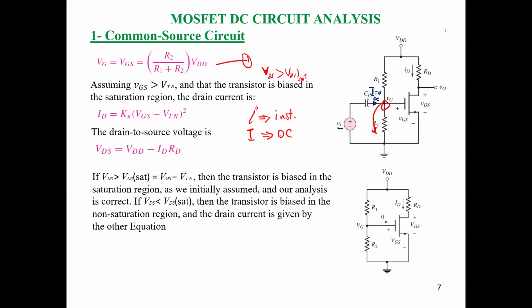So in this case, guys, we can say it's for sure a capacitor at steady state. This branch can be removed from our circuit. As you can see, this circuit leads to that circuit. So we don't have the AC source and capacitor part anymore in the case of DC analysis. Here you have VDD still as it is, still the DC component. You have zero current here.